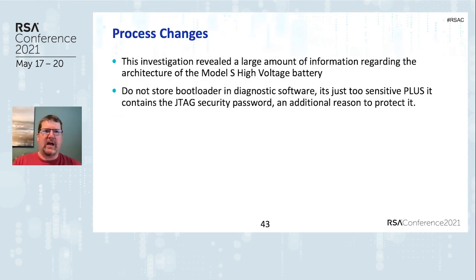And then some process changes. Don't store the bootloader in the diagnostic software. It's too sensitive. It contains the JTAG security password. Get it out of there. Have it as special cases for when it's needed, and have your engineering departments handle those.